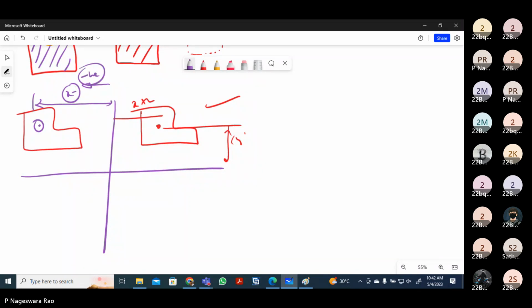We have to enter the negative sign wherever the x coordinate appears in the formula, A1 x1, A2 x2, where x1 and x2 are the coordinates. If that area is in the second quadrant, the respective centroid x coordinate will be in the negative direction. Hence in the formula also we have to give the negative sign.